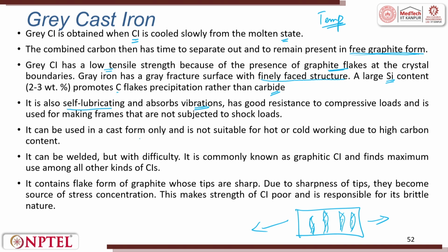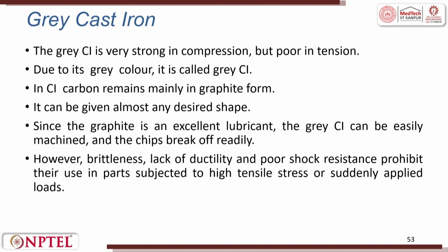It can be used in cast form only and is not suitable for hot or cold work due to its high carbon content. It can be welded, but it is very difficult. It contains graphite flakes whose tips are sharp corners. These sharp tips become sources of stress concentration leading to failure. Grey cast iron is very strong in compression, which we have already dealt with.